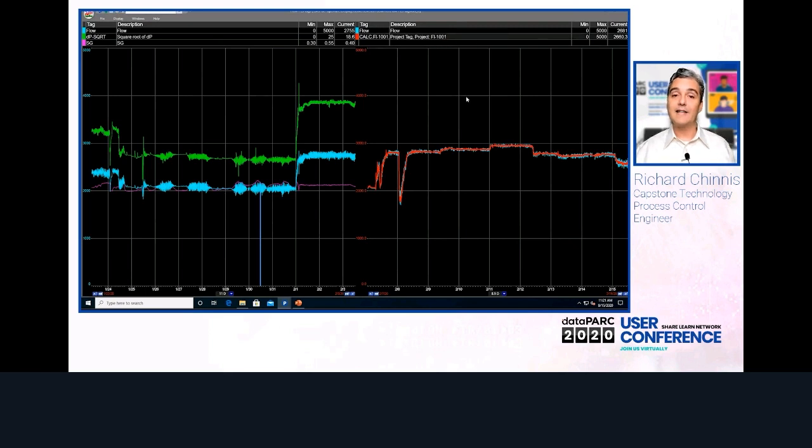So this is a valid test because what I've done is I've used an 11-day period over here in late January to create the model. And now I'm testing it against data that's in mid-February. So this is data that was not used to create the model, and it falls right on top of it. I now have a good model of flow. That is all for our PLS, and now we're going to move on to PCA model.